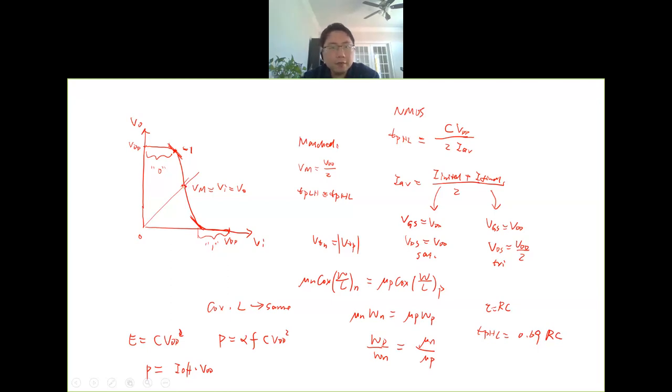For the noise margin, it's defined at the point where the slope of this VTC curve becomes -1. From here up to this point, you can think the input signal is 0. That means if you have some noise within this range, the output will still maintain high.